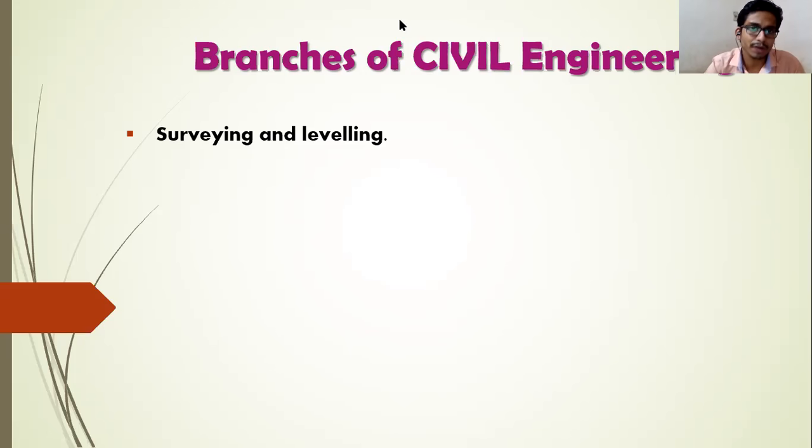When we measure something in the vertical direction, we call it leveling. In surveying, we measure heights with respect to mean sea level, and that particular part of surveying is known as leveling. This is very important as a prior work of construction. Before construction, surveying, especially leveling, is very important.